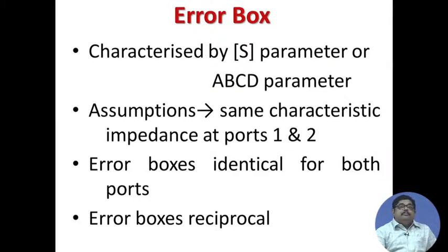That is done by putting all these errors, phase delay, etc., into a box that is called the error box. So, the error box represents all these lossy or error effects. Now, that error box is characterized by S parameters. So, if we are aware that there is an error, we can characterize that error, and we will see how it is done. And in finding that error box S parameter,